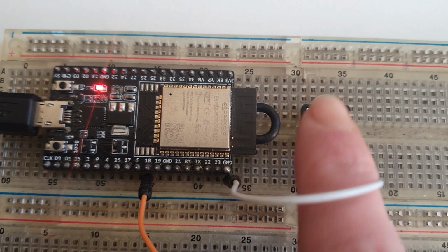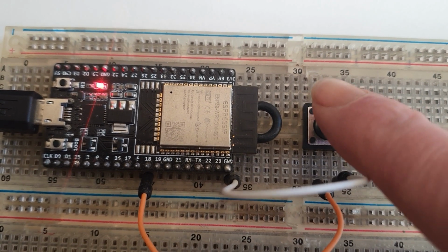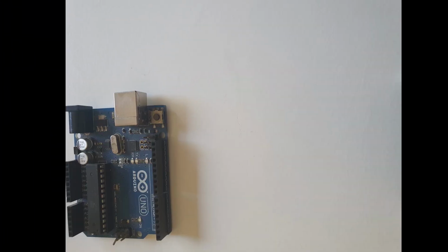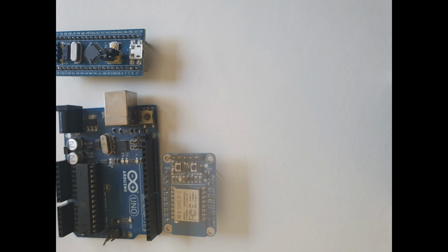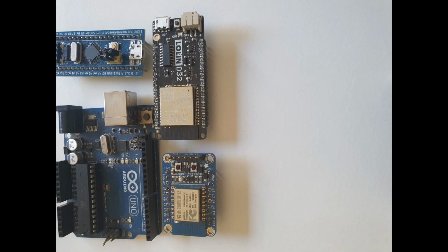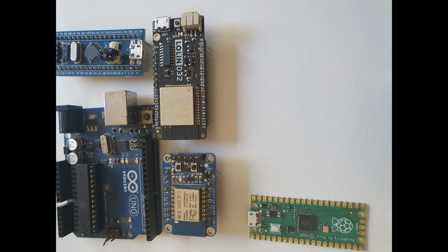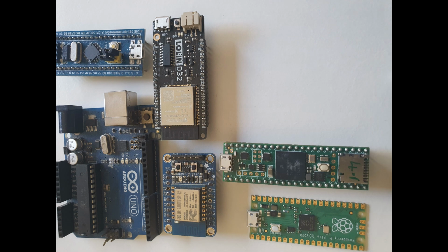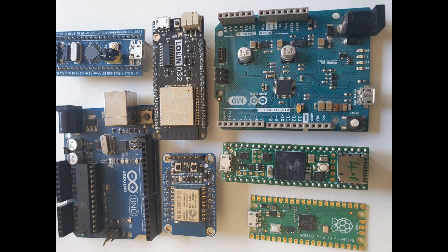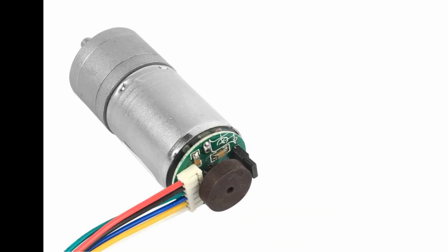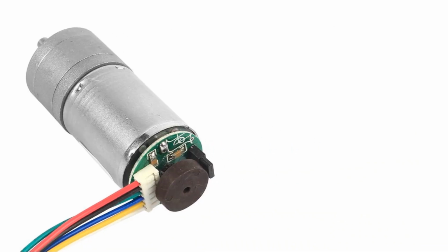Welcome to another video. Today we're going to cover why and how to use external interrupts. All Arduino compatible boards have external interrupts available, though specific implementations can be different depending on your board. These are very useful if you need to track high-speed external events in your project, such as the encoder on a fast-moving motor or an accelerometer.